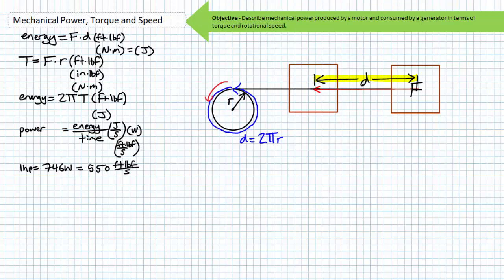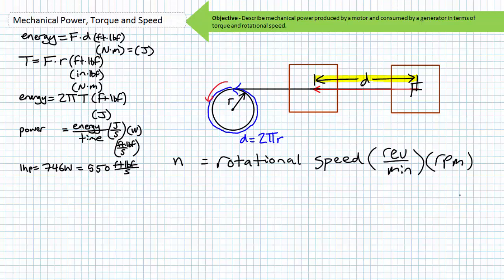Rotational power is not as easy to conceptualize, albeit it's intrinsically much easier to understand than our earlier discussion of torque, because a rotational shaft is obviously rotating at a given speed, or number of turns per given time period. If it rotates slowly, yet is still exerting a constant amount of torque per revolution, chances are it's delivering less power to a system than one exerting the same amount of torque per revolution, but doing so at a greater rotational speed. The missing link in our discussion of power is this rotational speed quantity, which some genius decided to represent mathematically with the letter n.